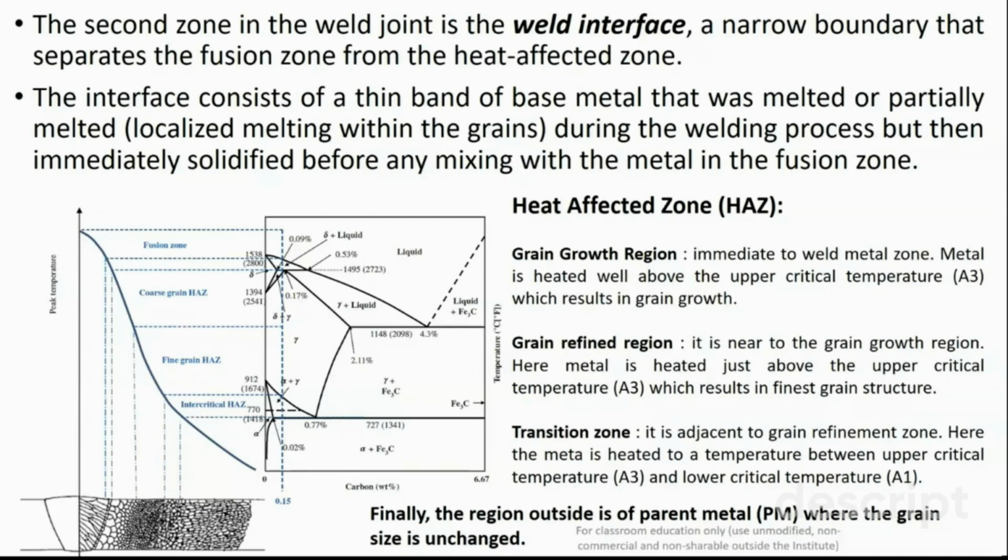In the first step, we perform the welding process under different metal transfer modes. We supply the weld metal into the welded section, and in the welded section the grains start to nucleate at the surface of the base metal. The partially melted grains at the surface of the base metal provide the site for nucleation, and then grains start to form with different types of solidification modes depending upon the temperature gradient and the solidification rate, basically the cooling rate.